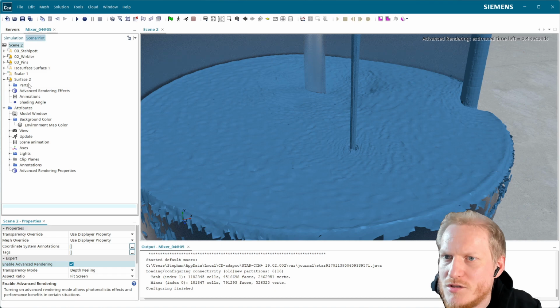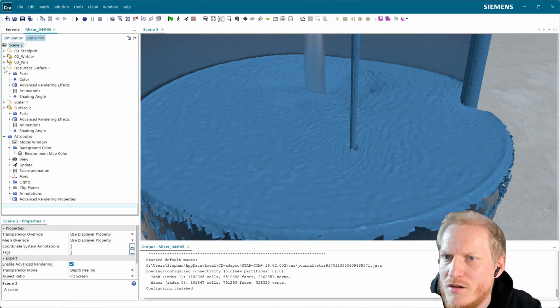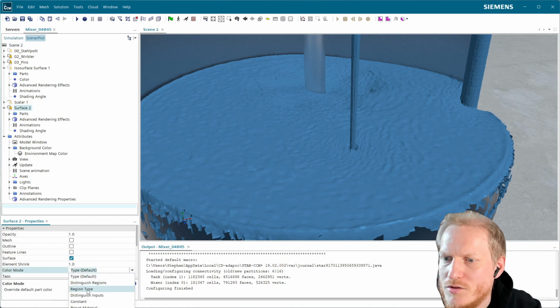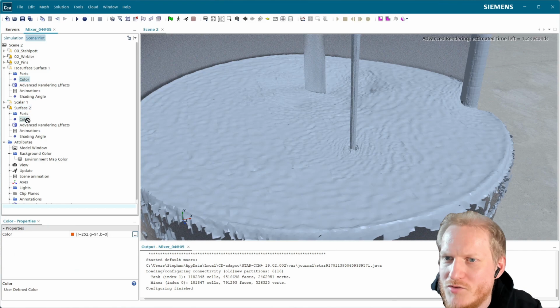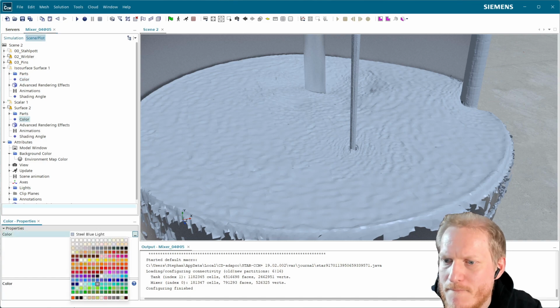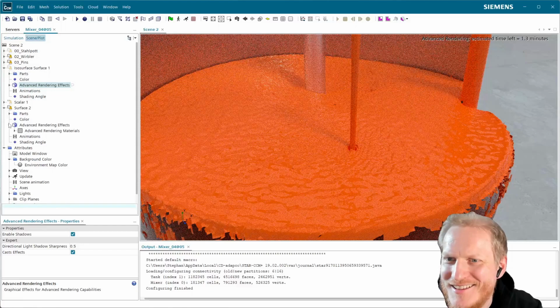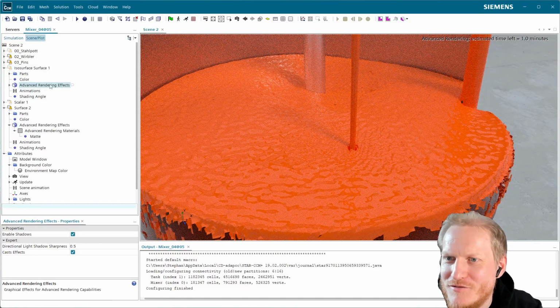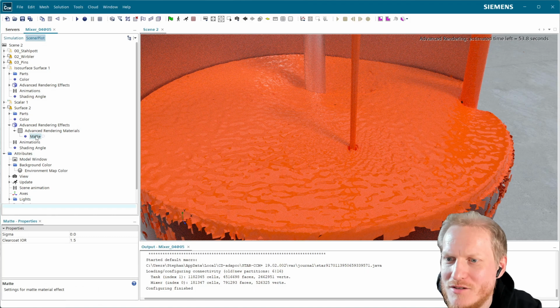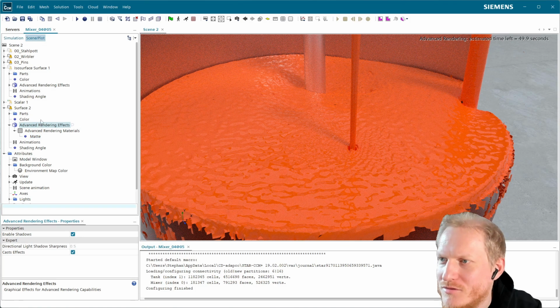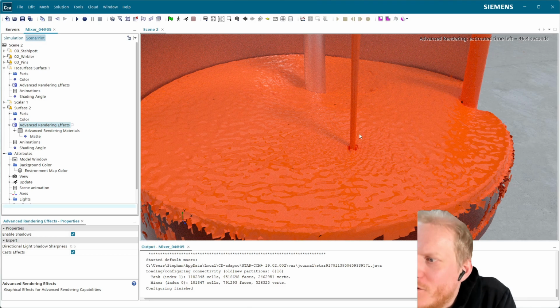And now we are just copy pasting the isosurface properties, which means we are going for constant. Then we can drag and drop the color down. No, we can't. Damn. We're going for orange again. Can we drag this one down? Yes, we can. You can copy paste the effects from up to down here just by dragging it down. So here we go. We have that orange surface.